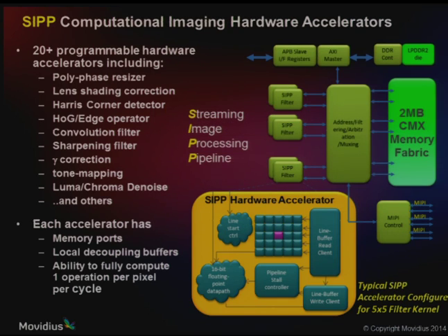And what we've done with the hardware accelerators is take the parallelism even further. Each of the elements that we've implemented as hardware accelerators, for instance, things like non-local means denoise, luma filters, tone mapping and correction, histogram of gradients, etc. They've all been implemented as fully parallel system blocks that don't have to go back and forth to memory.